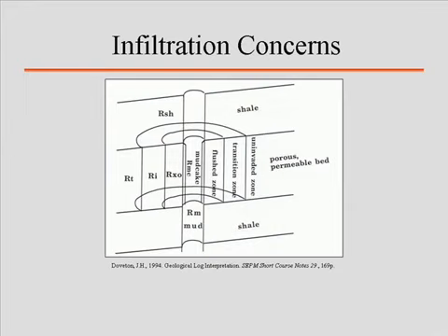Along the margins of the hole is what they call the mud cake. This is the area where you literally coat the surface with a layer of drilling mud that is going to be stuck there because it's going to be lining the entire hole all the way down. That mud cake is essentially like pottery clay. Okay? It's thick, slimy. But you're also going to have some problems where you start having the formation itself affected by the pressure that you're exerting down the hole.